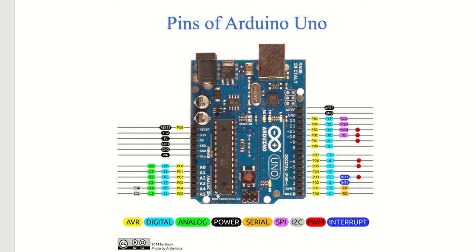Now let's come to the pin diagram and see the different pins which are used in the Arduino. The first pin which I would like to talk about would be the input output reference pin, or IO ref pin, which earlier used to come over the reset pin here. Now I think they have shifted somewhere else, or they don't use it anymore.